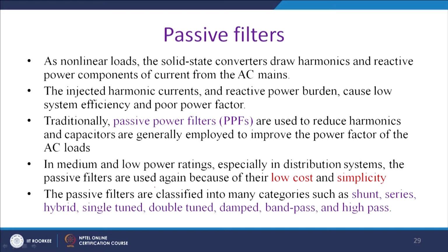The passive filters are used because of their low cost and simplicity, but there are many drawbacks of these passive filters. They are classified into many categories such as shunt, series, hybrid, single tuned, double tuned, damped, band pass and high pass. We will see the figures in the next few slides.